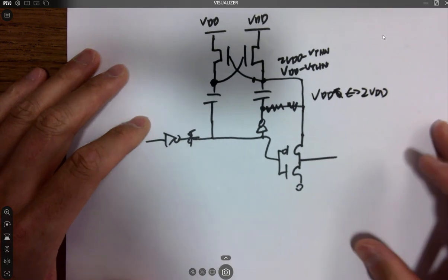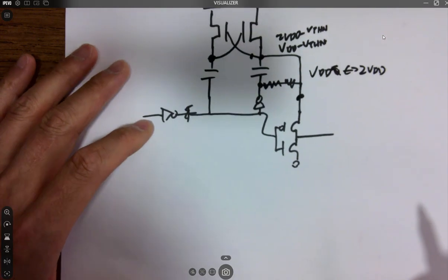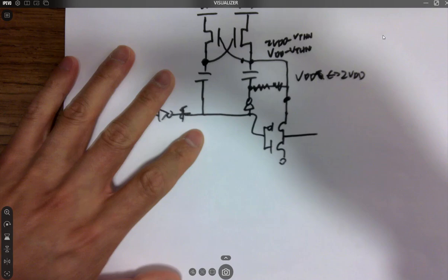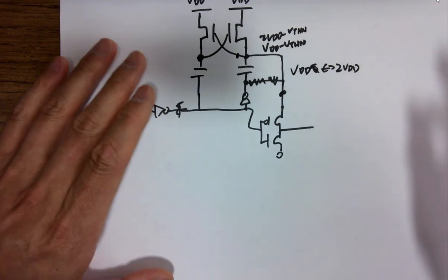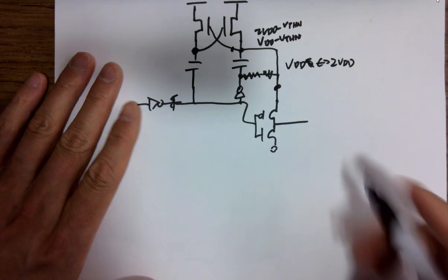Alright, and remember the PMOS, and there's no issue about the wire connections for the NMOS, but there is a potential issue for the PMOS, that you need to place the PMOS in its individual well.